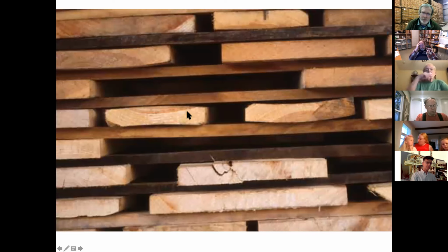Bond, look at the piece next to it, it's the other way, so what you're saying can't be true. Well, that's a sneaky one because they just flipped this board over. See, here's the heartwood. This is the sapwood. You can actually see some bark here. So the bark was out here, the center of the tree was here. You can see the curvature of the growth rings. So it did exactly the same thing, right? Yeah, the more tangential plane of reference shrank more than the bottom, and so it cupped.